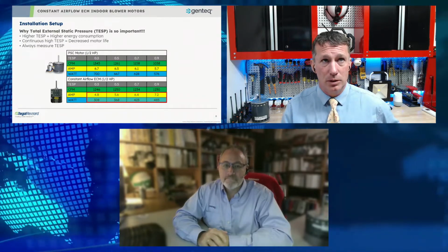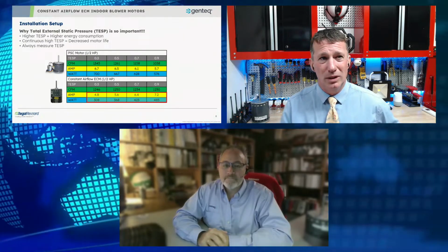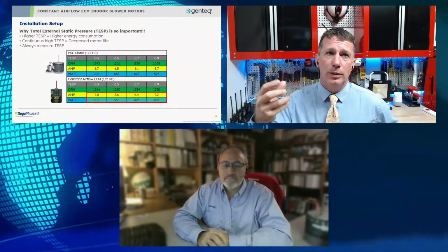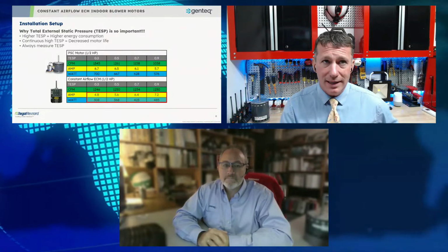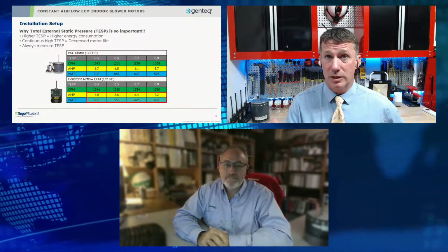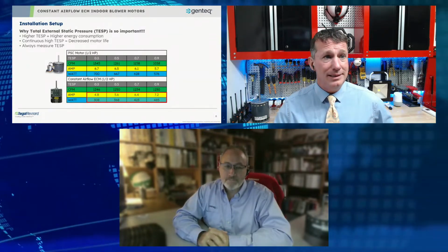And some of our motors, particularly those PSCs, would allow you to get by maybe, but now with our newer technologies, we're starting to recognize those situations, and they can cause detrimental motor failures. Right, motors are more expensive. So we'll hear that every once in a while, man, these ECMs don't last.